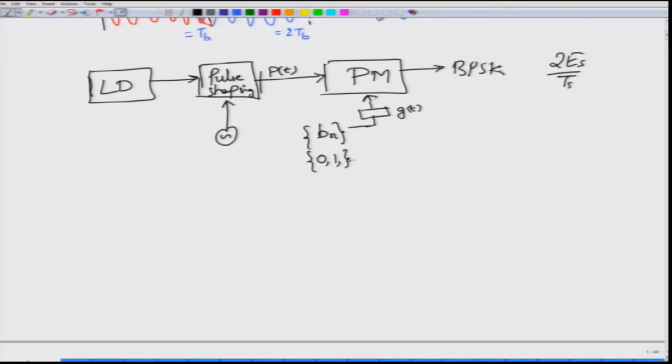Okay. Now, with BPSK signal you are able to transmit one bit for one symbol, right. So, it occupies a certain bandwidth. We will come back to the bandwidth calculation in terms of power spectral density after some time, but if you look at the power spectral density, which has a certain width corresponding to the bandwidth of this particular modulation technique, you will see that for that given bandwidth you are able to transmit one bit for every symbol that you transmit.